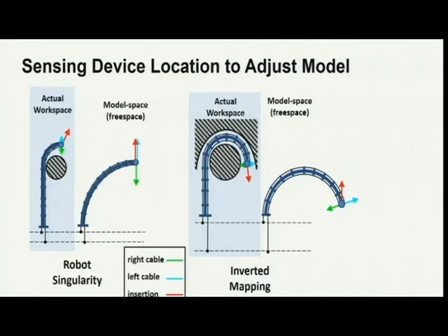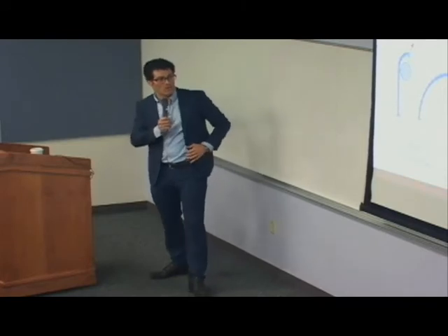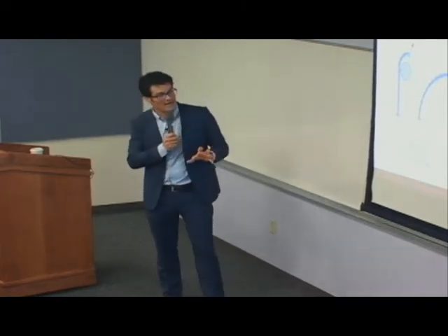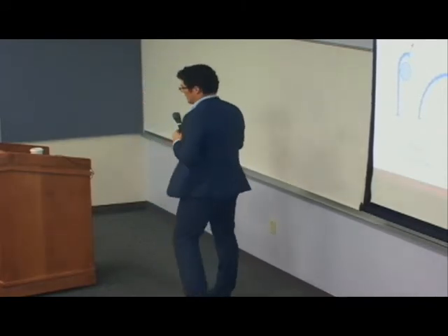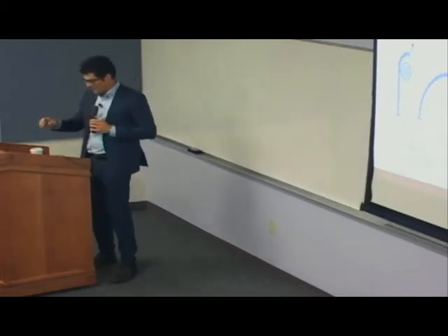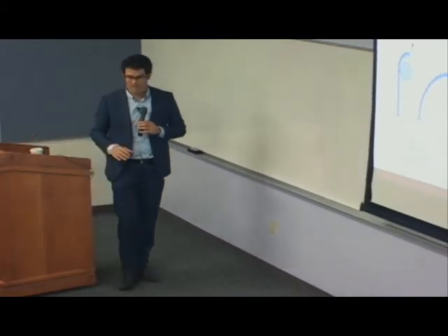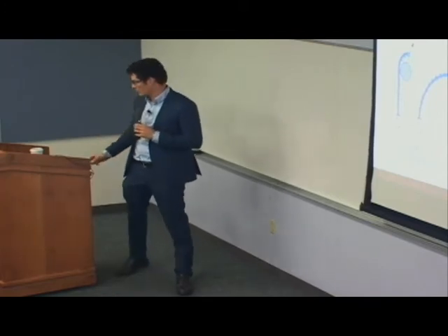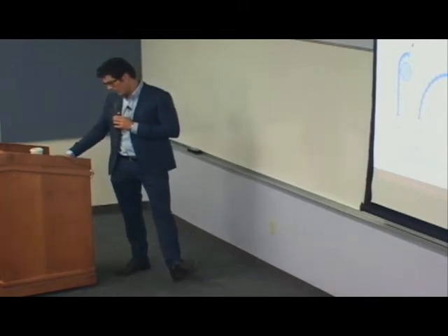So it's going the exact opposite direction. So you can see how that would cause some significant stability problems. You've got a sign flipped. And so again, when you're working in these more confined environments, the no-contact assumptions in the model-based control don't work very well.